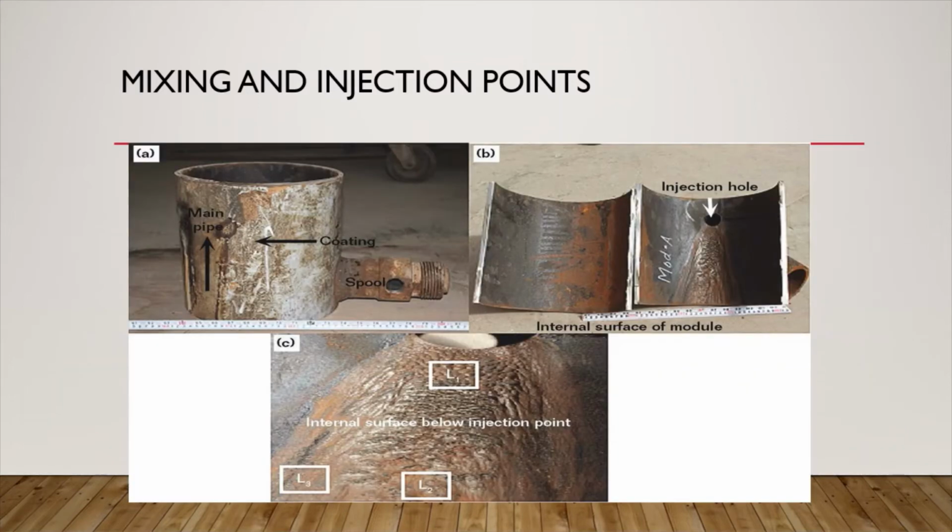In this picture, the result of the turbulence downstream from the junction is shown. Too much corrosion will lead to thinning of this pipe wall section and it will lead to leaks. The same applies to having a mixing point close to a 45 or 90 degree elbow, because the turbulence resulting from the fluid hitting the pipe wall at the turn will corrode that section faster than the other surrounding areas.